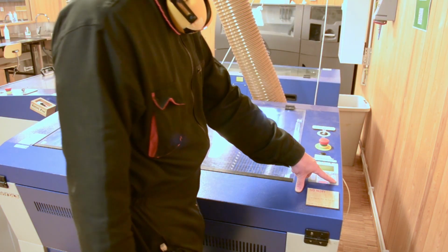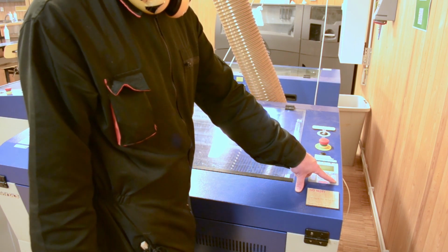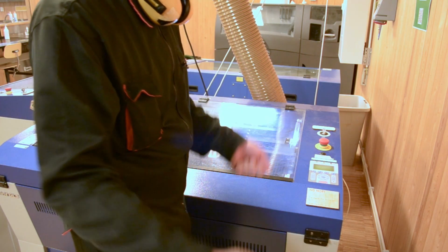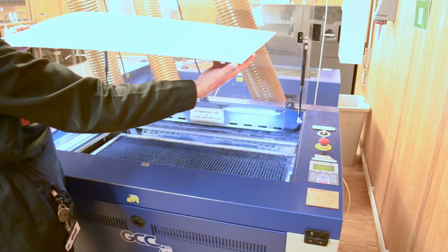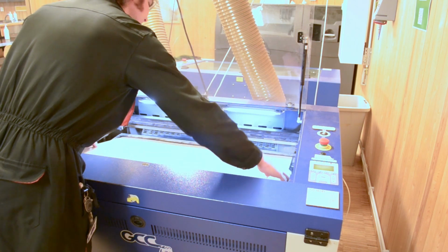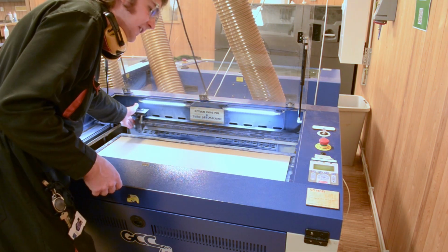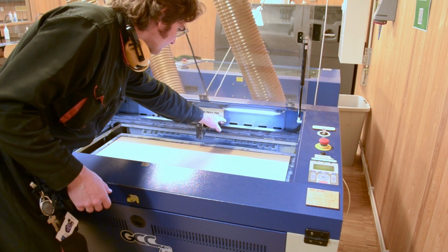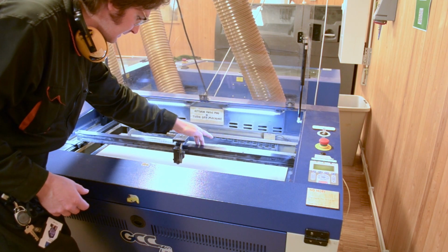After the laser cutter has successfully booted and homed its X and Y axes, jog down the machine bed so that you can more easily put your material there without colliding with the laser cutter head. Position your material sheet so that its top left corner is situated at the farthest left corner of the laser cutter workbed. Gently push and pull the X and Y axes so that the laser head is situated above the center of the material sheet.